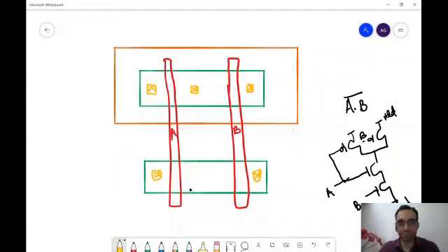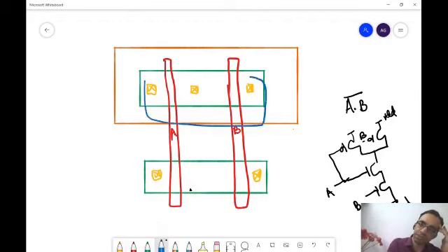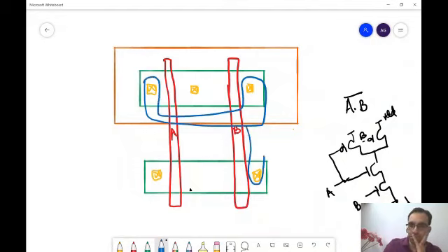Sir, middle one should be output. Middle one should be output. Why? Sir, because it is shared. The PMOS drain, both the drains are connected. So I can share that here with metal. See, I could short them like this. Sir, middle one would have less capacitance. So output, this could be the way I could have output there. Yes, sir. This can also be done.